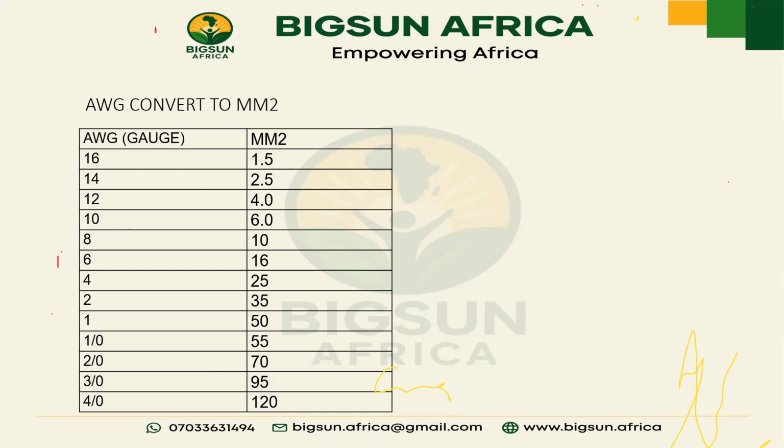Did you get the question? Our question is this. We are trying to connect 4 batteries, and each battery is 12 volts, 100 amps. These 4 batteries, we are connecting to a 48 volt inverter. So automatically, you know that the batteries are going to be in series.